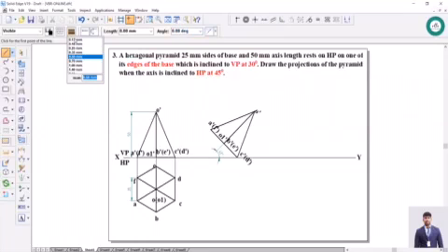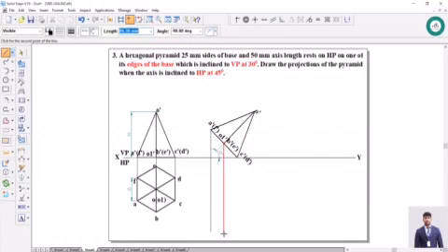Next, go to axis, go to projection line, project from all the points. So after projecting this from the front view to the top view, project to the right side, have a look. E is somewhere here, E meets here, and F is here. So I will click intentionally once here and once again here. Next, when it comes to O, I will click here once. This is the O1 point.